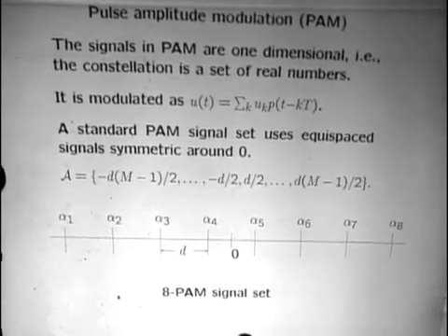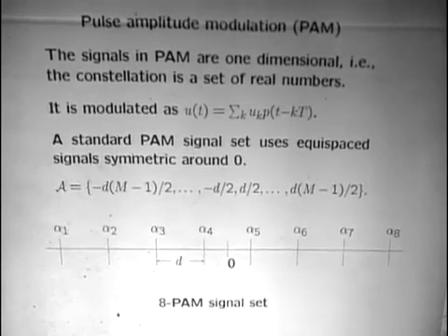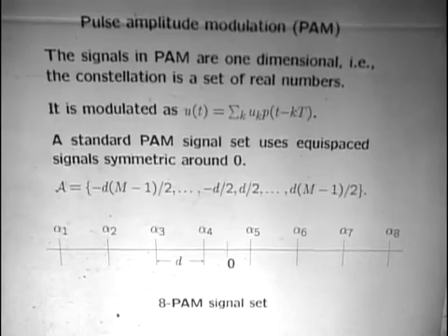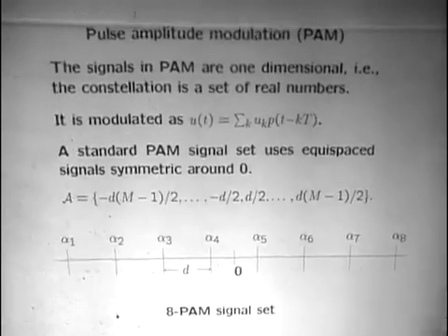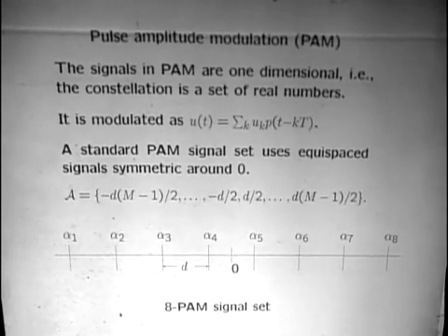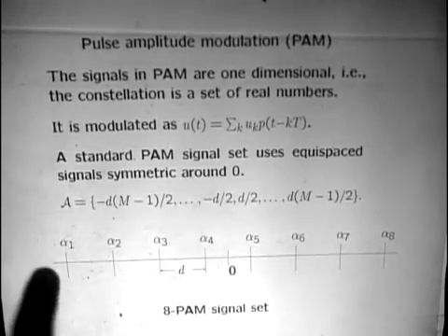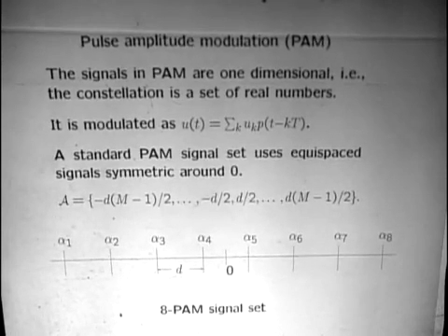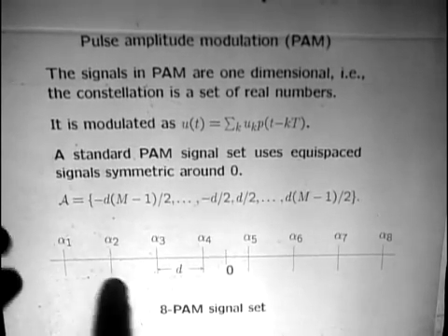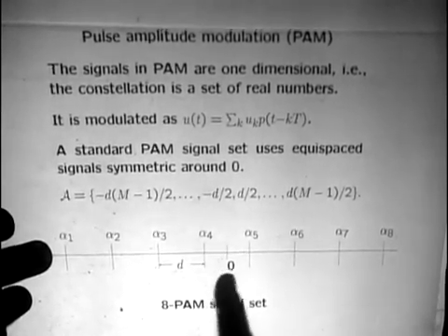And if you look at the picture, it makes it clearer what this means. It's the same thing we were using all along when we were talking about quantization. If you're looking at one-dimensional quantization, that's a very natural way to choose the representation points. Here, we're doing everything in the opposite way. We're starting out with 8 symbols and turning them into 8 signals. And when you take 8 symbols and turn them into 8 signals, the perfectly natural thing to do is to make each of these signals equispaced from each other and center them on the origin.